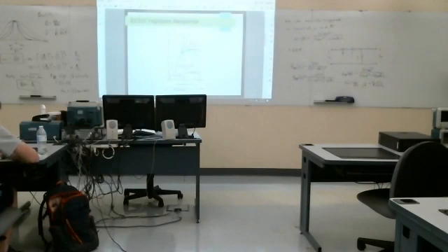I know if the coefficients are real, the poles and zeros will either be real or occur in complex conjugate pairs. The complex conjugate pair terms become 2nd order terms. So any higher order filter I can write as a product of 1st order terms and 2nd order terms. That's a consequence of using real coefficients that are always positive here.